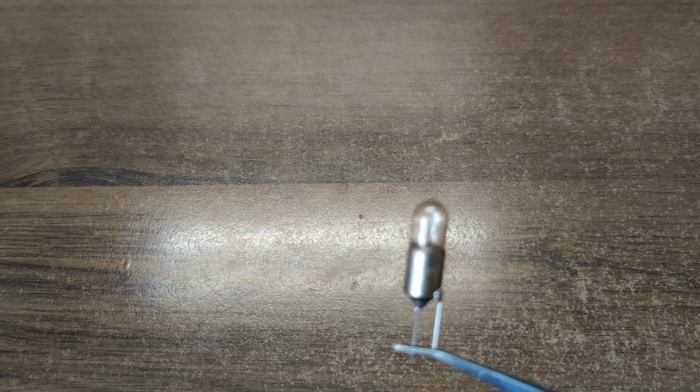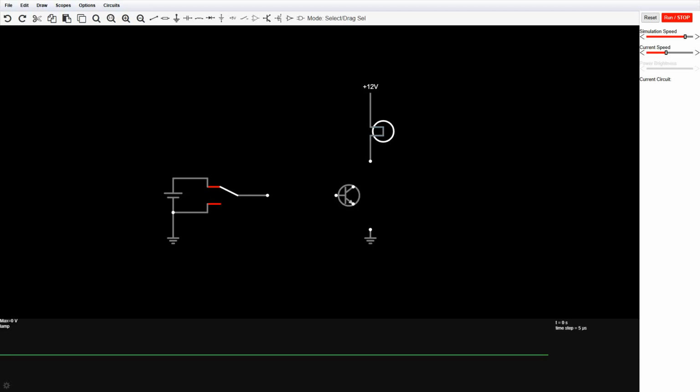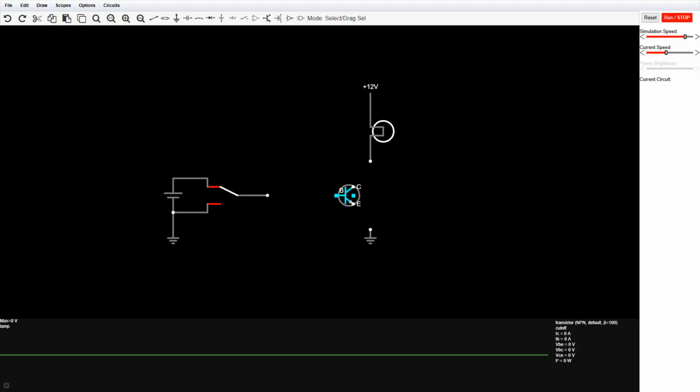Let's try connecting one to a 12-volt lamp. To control it, you need two connections, the signal and ground. The load also needs two, input and output, plus and minus, red and black. You can name it as you want, but one wire alone won't do the trick. Since the transistor has three pins, one will serve as a shared connection.